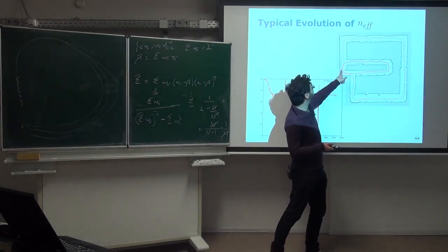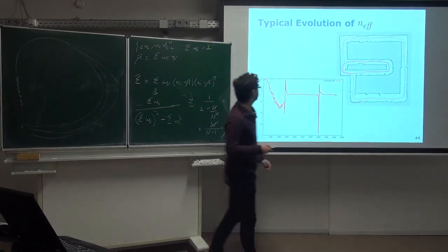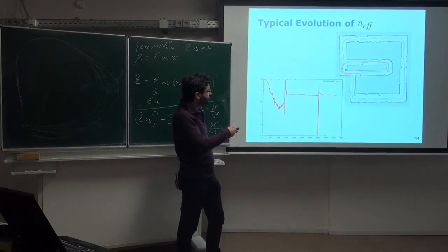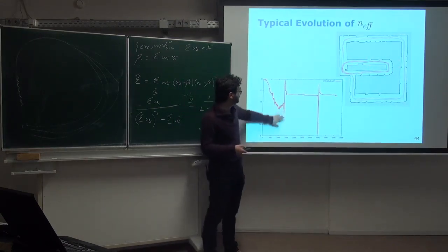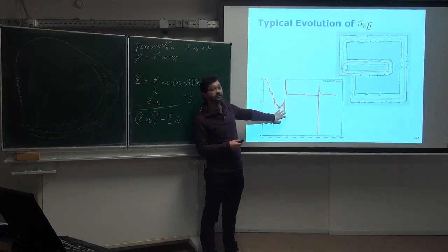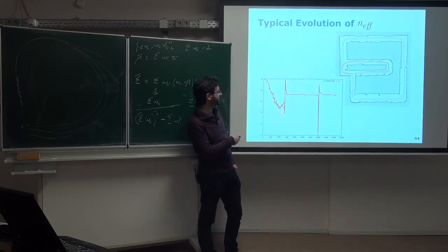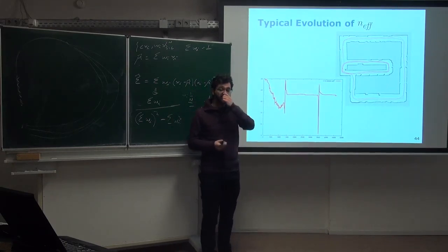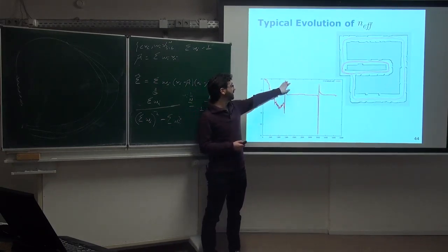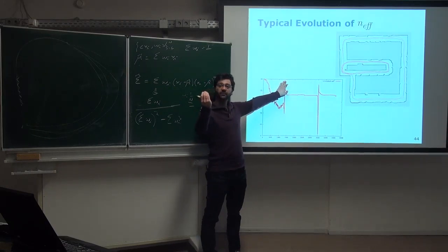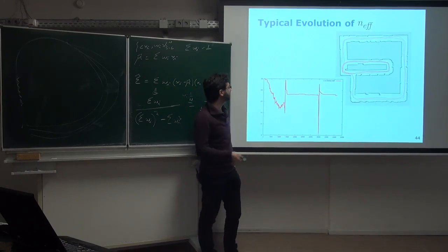Then the robot goes around here. It does a loop here, and then you have a decrease in the number of samples up there. And then it goes through a resampling step, so you go from a number of effective samples of around 15 up again to around 30, and that's just because of the re-normalization of the weights. Now all the particles have the same weight, 1 over n, the number of particles.